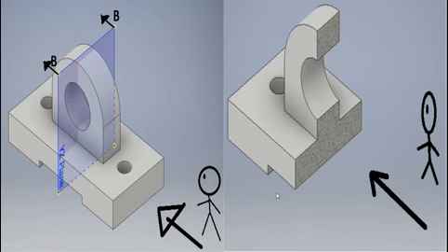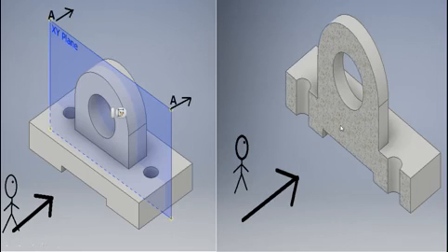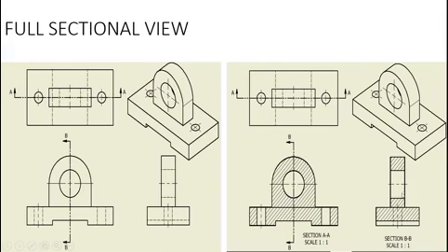and then after we cut it, we have this drawing here, and this is our view. So we will be standing here and viewing this drawing from this side, which is from the right view. So this is the side that we're gonna hatch. You can see the rough surfaces where we're gonna do the hatching, and here it is, the hatching.